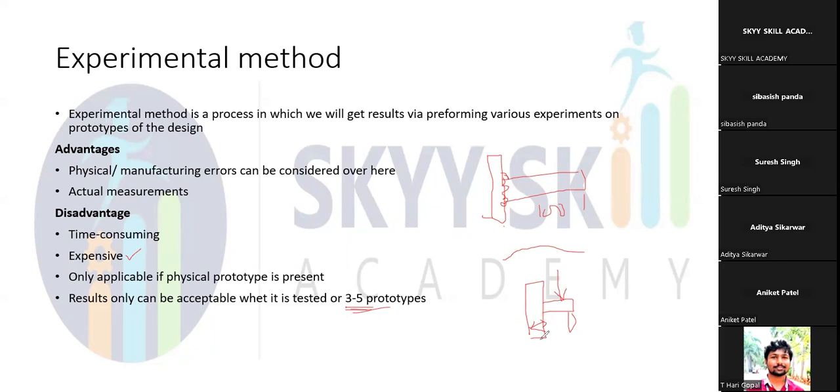So I need to change something in that design so that its strength is going to increase. Either I'll change the design, that over here I'll have a member stiffener, or I will change the material, or any other thing you need to do there. You just do this, and again you come back to the analysis. Over there you will analyze it. Again you will see that everything is correct. Then I will move out of this loop.